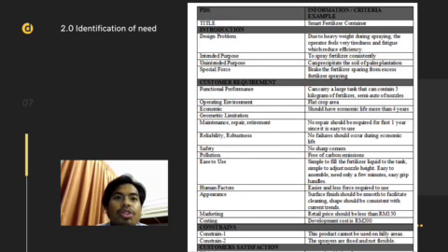It is simple to fill the solid fertilizer into the tank. Simple to adjust the nozzle height. Easy to assemble, needing only a few minutes. Easy grip handle. So for the human factors, easier and less force required to use. Appearance: surface finish should be smooth to facilitate cleaning. Shape should be consistent with the current trend. Marketing: retail price should be less than 150. Costing: development cost is 200.